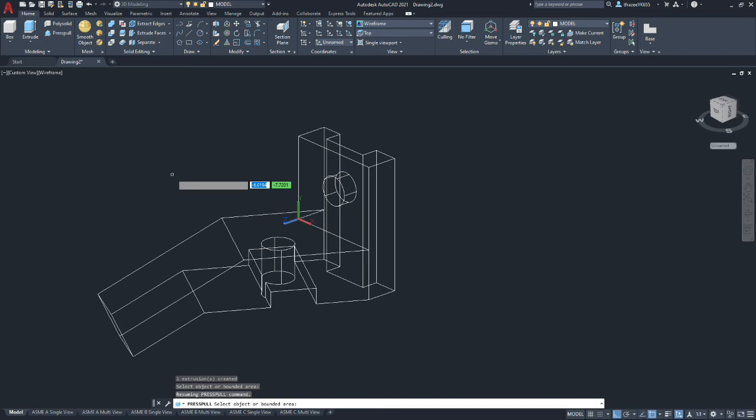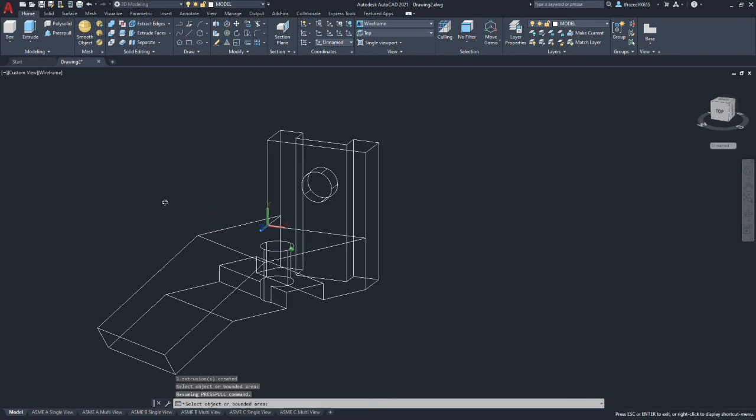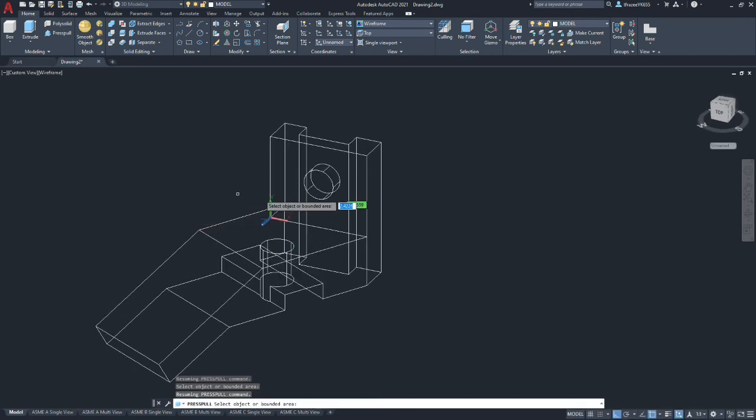It looks like it is intended to be a symmetrical feature, so I'm going to set up to draw half of it and use a mirror on the sketch. But first we need to change our UCS. So we're going to change our UCS again, and we'll go ahead and turn ortho off for the moment. And we'll pick the left corner. Then we'll pick the right corner as our positive X dimension.